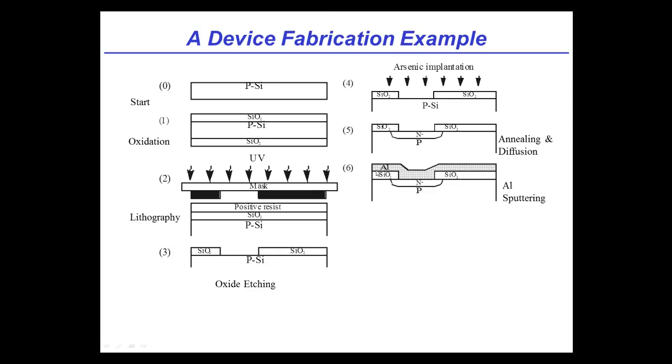Yeah, so that part's pretty easy. What we're going to do is take our wafer that's right here. This is just a section of it, but here's the wafer. We're going to put it into that sputtering system we described to you. In this case, we're going to sputter aluminum. So we're going to accelerate argon into the aluminum target. The aluminum atoms are going to blow off the target, and they will redeposit onto this wafer, and they'll just do it everywhere.